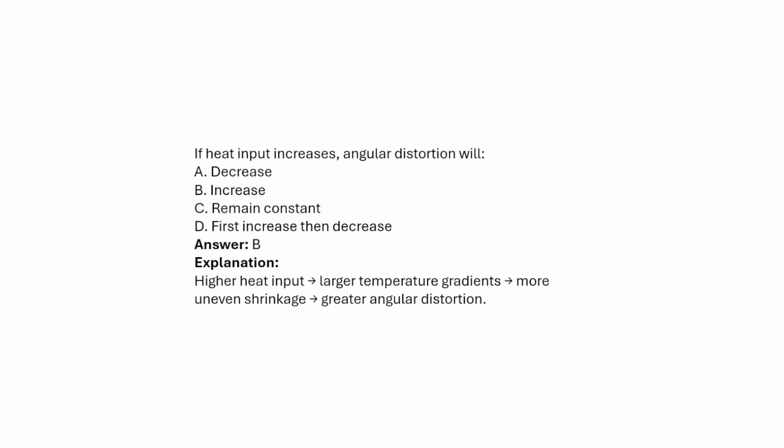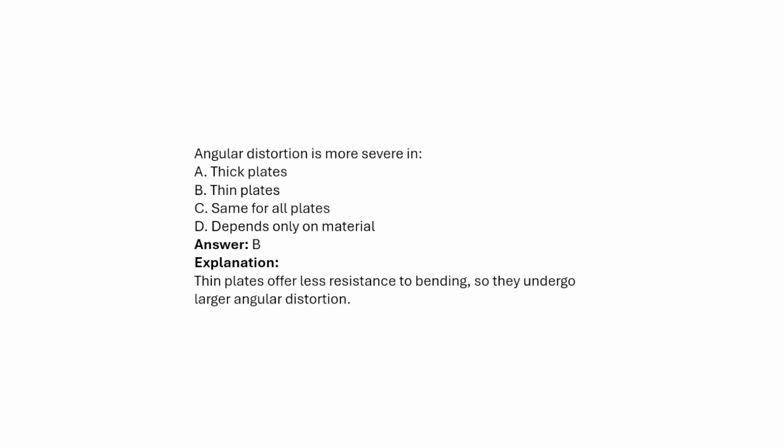If the heat input increases, the angular distortion will increase, because distortion is directly proportional to the amount of the heat input. So the answer will be B, increases. Higher heat input results in larger thermal gradients, more uneven shrinkage, and greater angular distortion.